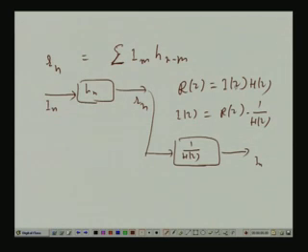It is an FIR sequence, because you know the intersymbol interferences are only from adjacent neighbors and not from very far away pulses. So, those coefficients related to far away pulses die out. So, it is an FIR sequence, but its z transform, say H z, I have no control on the roots, that is, on the zeros of this FIR polynomial.